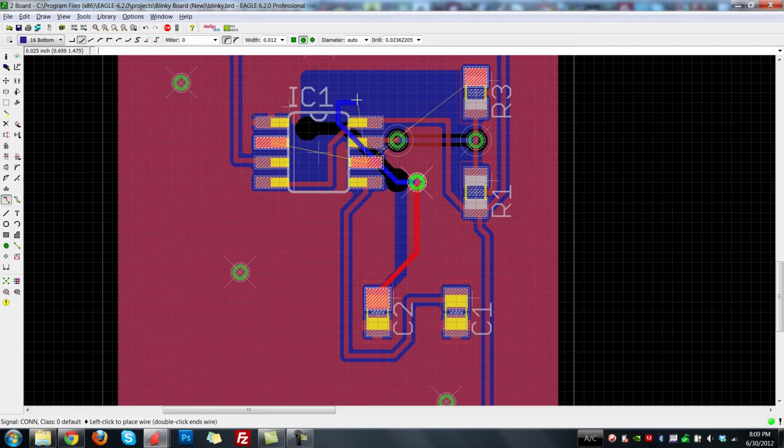We can see it's defined a via for us now here too. And now I want to bring it up to this connector right here, but I want it to make the bend first, not towards the end. To do that, you can choose a different bend option, and we can see now that it adds the bend back at the beginning of the wire.